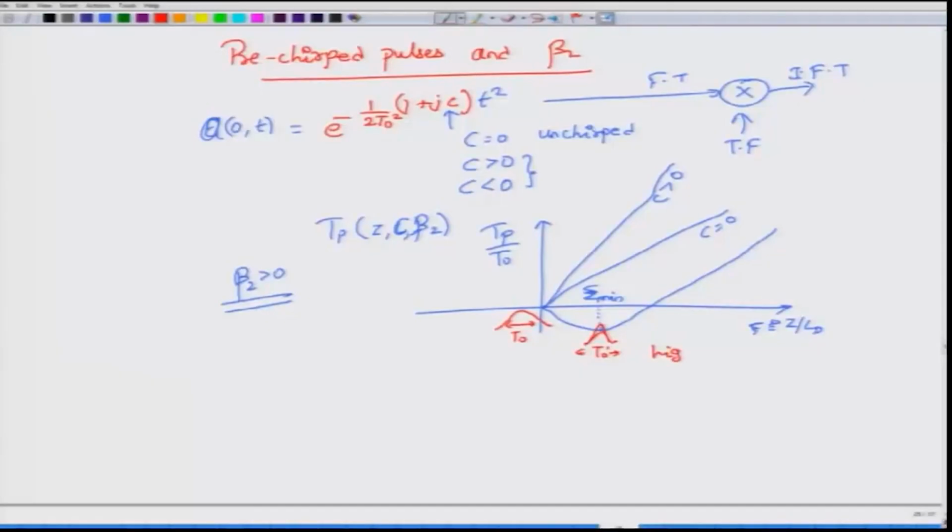So, what you are actually getting are higher peak power pulses. So, the pulse, this one is higher in peak power, plus it has a narrower pulse width compared to the initial pulse width. So, what we have actually accomplished is not so much the pulse expansion, but the pulse compression. And pulse compression is a very important topic in almost all ultrafast optics applications, where